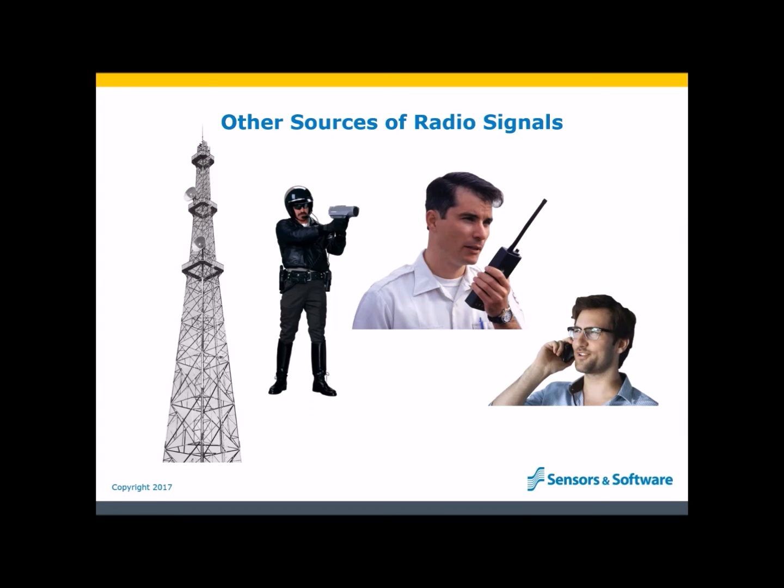The surface of the earth is immersed in radio waves at all times. So you will always see RF noise in your GPR data, even if the antenna is shielded. Keep in mind that the RF noise is usually about 1,000 times weaker than the GPR signals we are emitting. So you don't see the noise unless there are no GPR signals present.